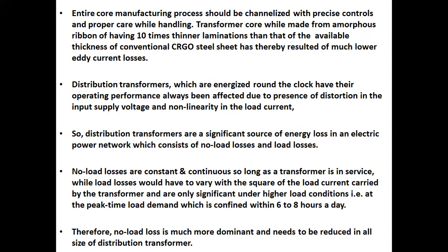Distribution transformers, which are energized round the clock, have their operating performance always been affected due to presence of distortion in the input supply voltage and nonlinearity in the load current. So, distribution transformers are a significant source of energy loss in an electric power network, which consists of no load losses and load losses.